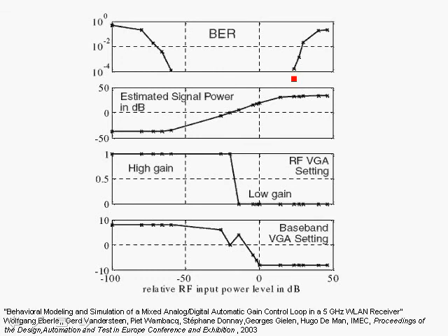As the input power increases, there'll be a point where the AGC control mechanism cannot peel off enough gain, and the signal power would be large enough to saturate the amplifiers in the baseband analog and also saturate the A to D. Beyond a certain signal power level, at very high SNRs, again the bit error rate will be very large and we lose packets.